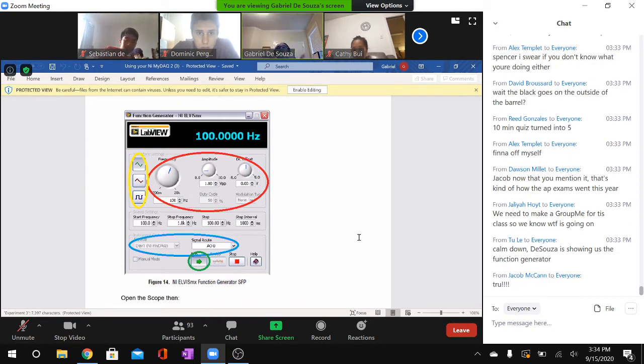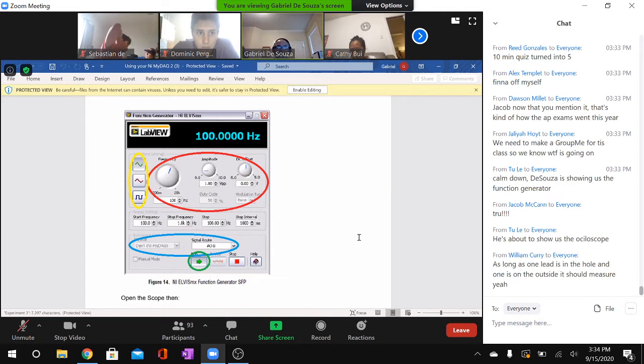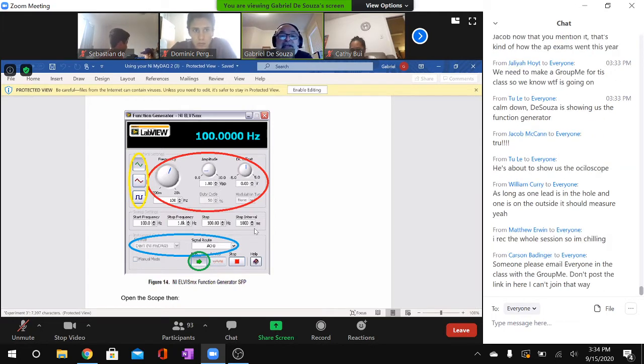So the device is going to compute what it needs to do to be able to go 100, then a fraction more, and then keep going up, varying the frequencies in this amount of time. That should take 1000 milliseconds, which is basically 1 second. So in 1 second, your frequency is going to start low, then go all the way to 1000 hertz.